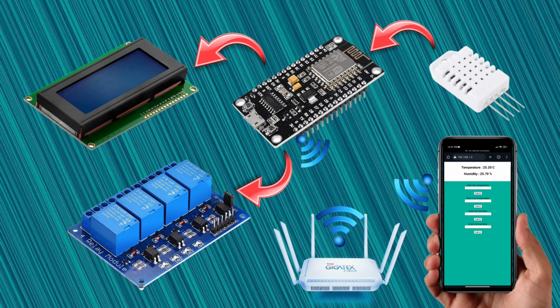The components are connected as follows. Temperature and humidity data are transferred from the DHT sensor to the NodeMCU Wi-Fi module. The temperature, humidity, and their averages are displayed on the LCD. The outputs are controlled by commands sent from the module to the relays.